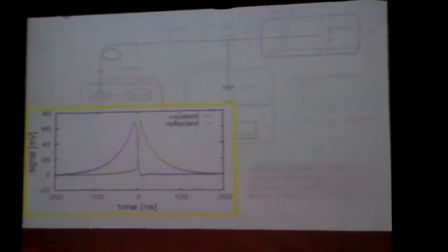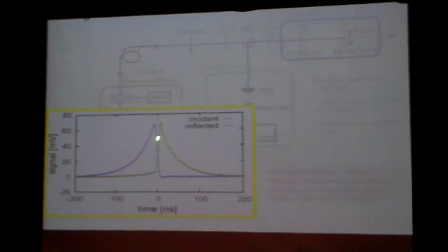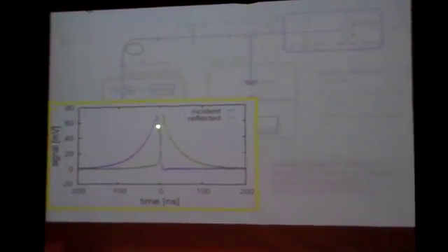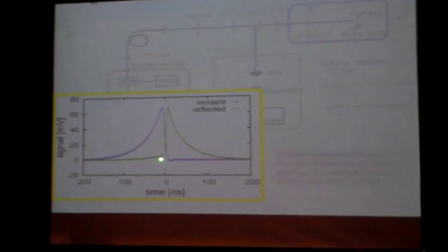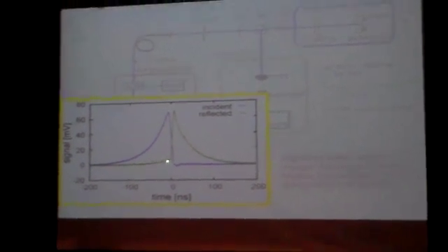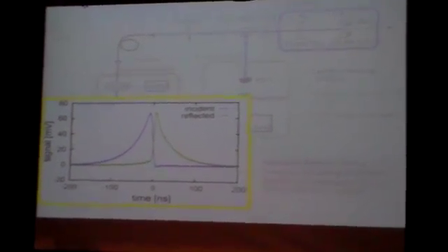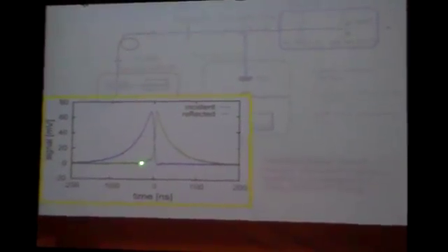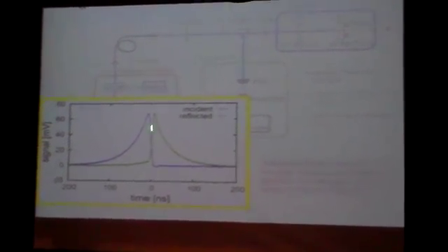And then, for one moment in time, all this energy is inside the resonator, and then, of course, the resonator starts re-emitting. So what we expect is at the moment when this sharp falling trailing edge comes to the resonator, and there's no more light on the input side, then the resonator will start emitting. And you see what we measure experimentally is very close to what we expect ideally. So this is not a step function, but there's a slight slope, but you can see it looks very close.